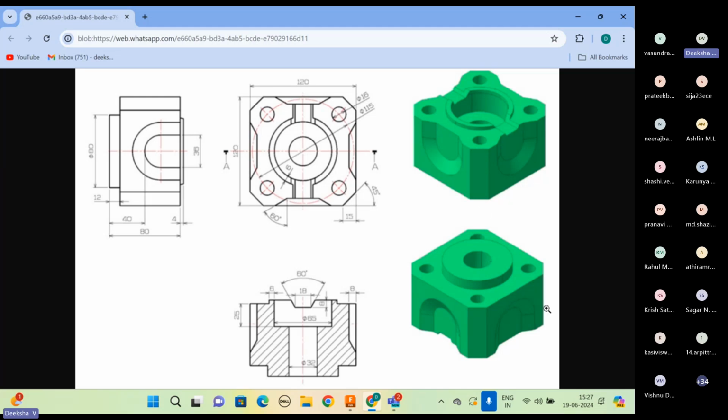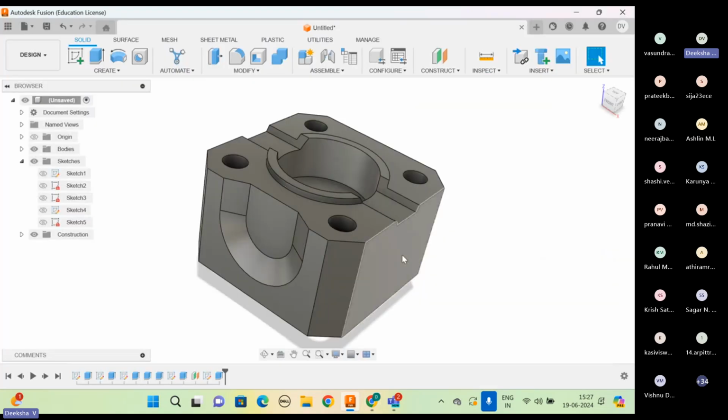Now the thing is, we'll need this U shape on every side and not only on one side. So if you wanted to, one thing you can do is create an offset plane on every side and again extrude it using taper angle, but that will be too much work. But since we have our circular pattern option, using that we'll just create a pattern on all the sides, which is a much easier way of doing it. Any doubts till now? You can ask me.